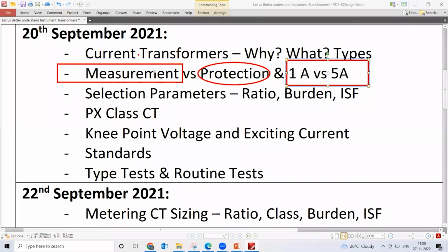Yep. Let me give the answer also. It's a low forward power relay or a reverse power relay. Low forward power or reverse power is the protection function which needs a metering CT, whereas differential protection definitely needs some special class of protection setting.